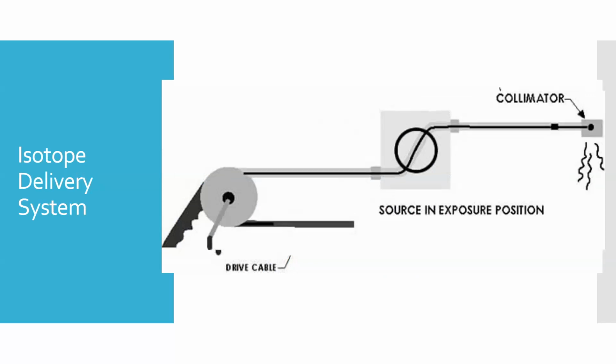So you move it along, and when it gets to the end, there's something called a collimator, which is basically another little chamber where it's only going to allow that radiation to escape in a given direction. Okay, and so now it would be at its position, and if we put an object below this collimator, and then put some film down here at the bottom, we would be able to create a radiographic image using this gamma ray source from a distance.